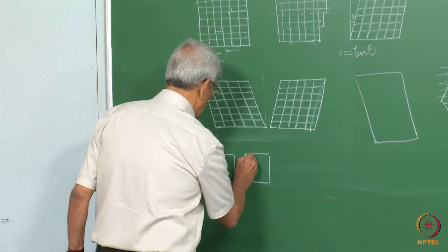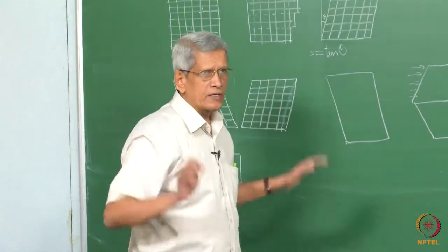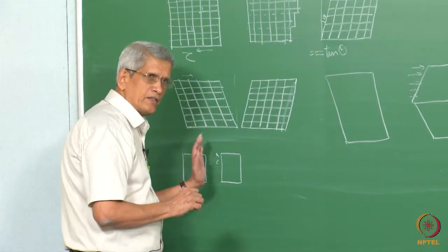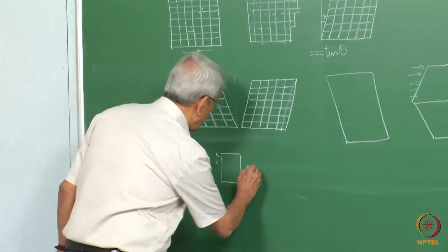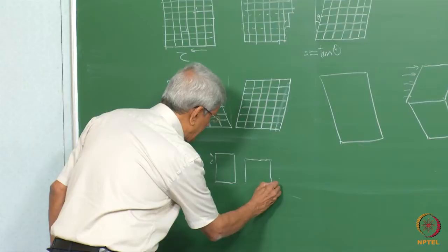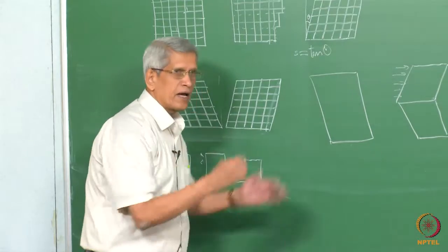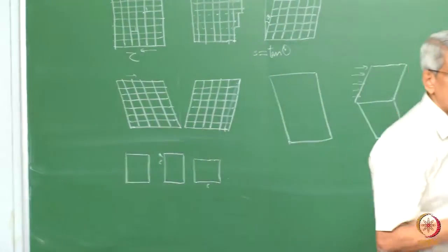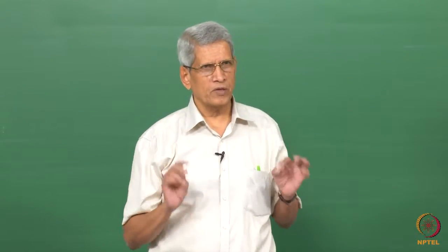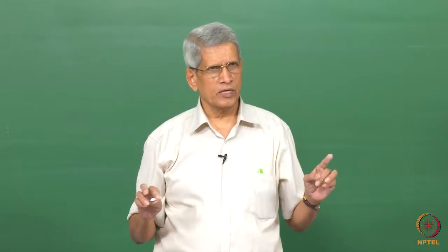The crystal can form when it is nucleating in a single crystal. In some region it can form with its c axis along the c axis of the FCC. In the cubic system, in one it can form with its c axis along the a axis. In another it can form with its c axis along the b axis. That means three possibilities are there. All three can occur. All three possibilities will occur simultaneously at different regions, but one of them will occur at a particular time in a particular region.